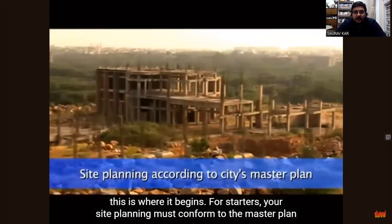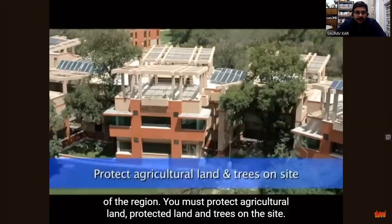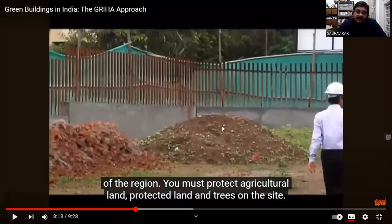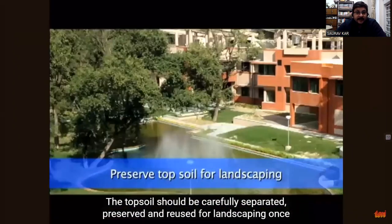Site planning according to the city's master plan. Okay. Very important issue. We have to protect agricultural land and trees on site. That means which are existing, we shouldn't cut them. We should keep them as they are, unless and until it is hampering the construction to a huge extent. The topsoil should be carefully separated for landscaping.